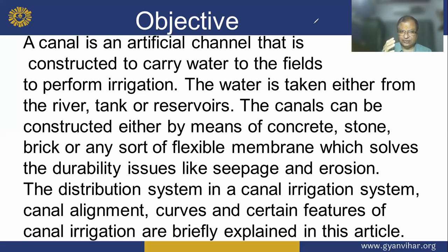Now, each canal can be constructed by means of concrete, stone, brick, or any sort. Why? For the lining, to stop seepage. Otherwise water goes into the earth and recharges the wells.